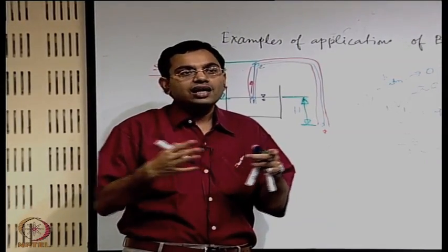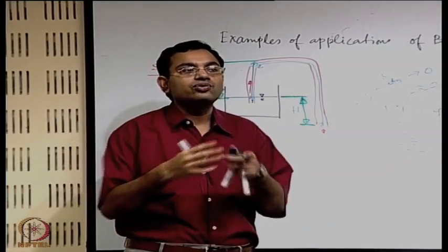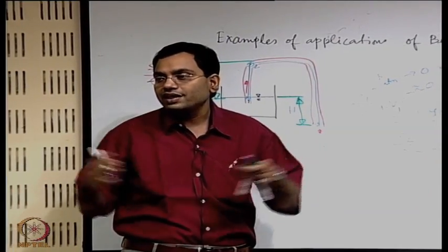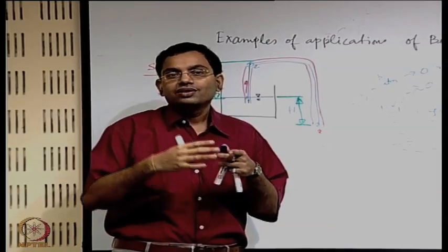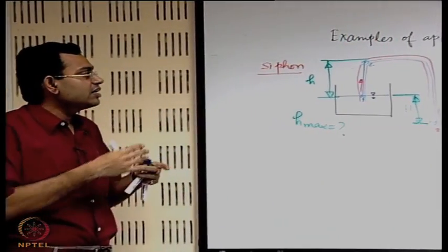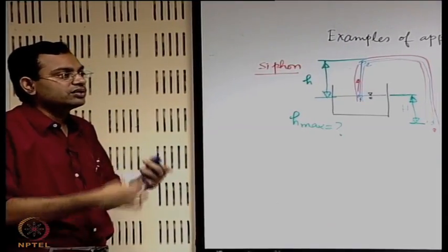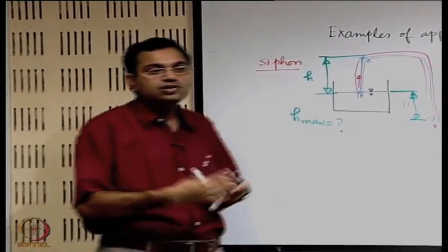Basically then they were occupying a large volume, but when they collapse again to be converted to liquid, there is a volume change. So it creates an unsteadiness in the flow and it can create a lot of vibration and noise, and that is not so good for the flow, and that type of phenomenon is known as cavitation.